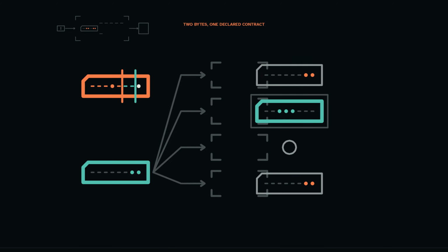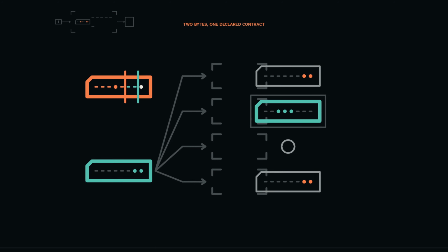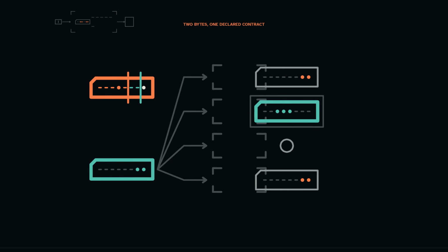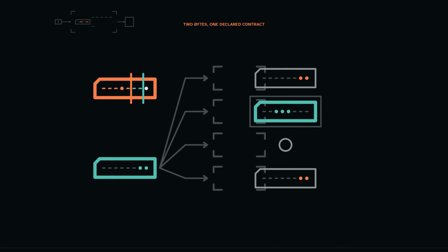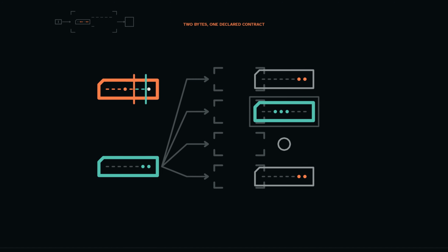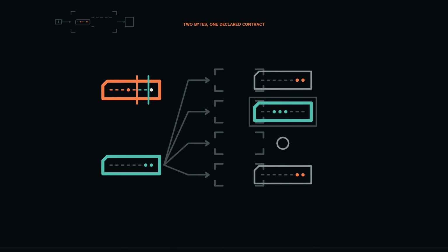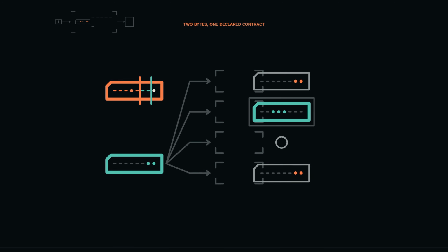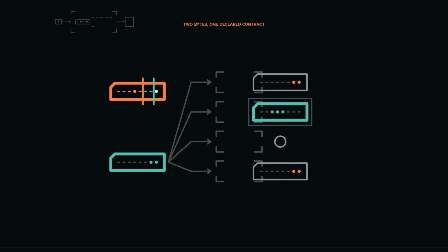Every SE8 instruction is exactly 2 bytes. In byte 0, the upper 5 bits form the opcode. The next 2 bits form field A, usually selecting one of registers R0 through R3. The final bit is I, the immediate mode choice for instructions that permit it. Byte 1 is field B, all 8 bits. Opcode decides the operation family. A and I refine that operation. Only then can B be interpreted as an immediate value, a direct address, a branch target, or a register selector. Field boundaries create the grammar. Visual spacing merely reveals them.